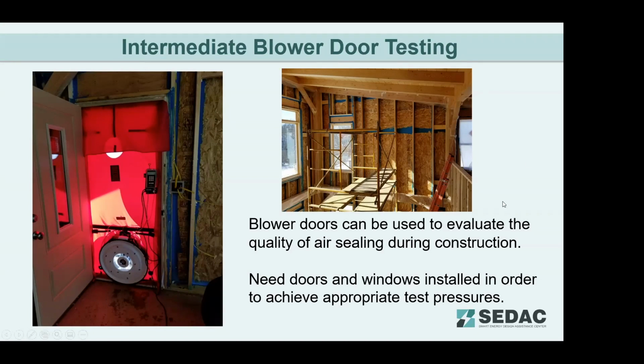Each time we do this test, we evaluate where we're at, and then we do some more air sealing while we're there to bring the house down to a specific leakage rate. Usually what will happen is we'll get it down past the threshold for code before we even install drywall. I just recommend it if you've got the time and the effort for it.